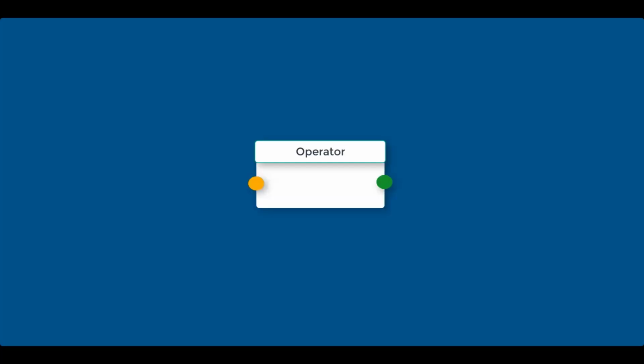Every command box basically means an operator with an input and an output. You put one item into the input, which will turn green, which means that it's ready to compute. And at the other end of the operator will come out an output item. So with our example of the point on plane, we put an item called a plane in the input, and the output will be a point on this very plane. And you have a lot of different variables that you can change in this command box.